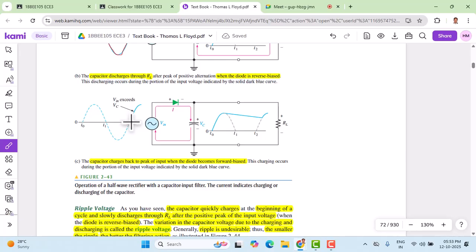because here the cycle has been completed, that is the first quarter of the cycle. And again, when the capacitor keeps discharging, the voltage here starts falling, right? So earlier we assumed the voltage as 4.3 volts. Now 4.3 can become 4 volts, 4 can become 3.5 volts, 3.5 can become 3 volts. It keeps dropping. So this is the capacitor discharging. So by the time it starts discharging, what happens?